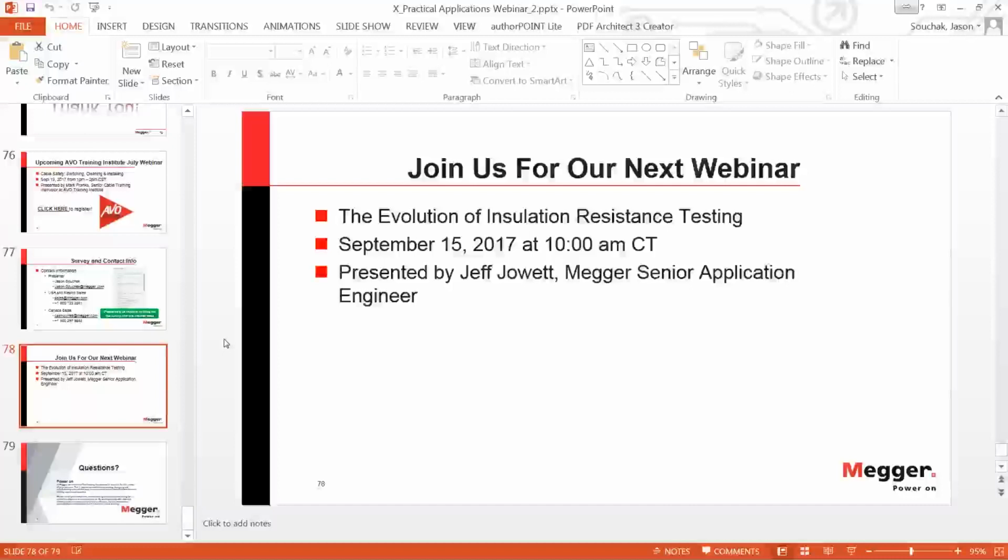So the PD would be for high resistance defects like voids in splices and terminations, and the leakage current tells you whether you have a low resistance situation anywhere, typically a mechanical defect from the installation process. So that is really a catch-it-all type of test, which is described in IEEE 400.2, the monitored withstand test for commissioning a new cable. I think it's a very powerful tool to do that.